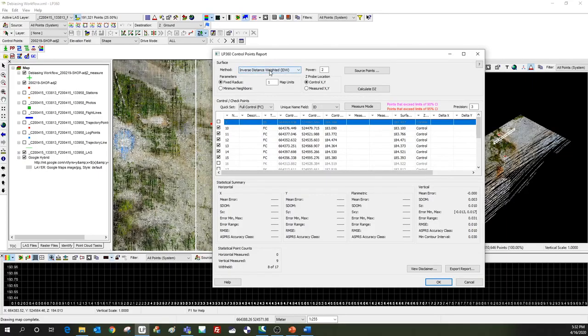With this inverse distance weighted, or IDW, this should give you a little better estimate. It's less noisy, a better estimate of the ground elevation, especially if the guideline about setting checkpoints in a clear and level spot is followed, as I've already mentioned.